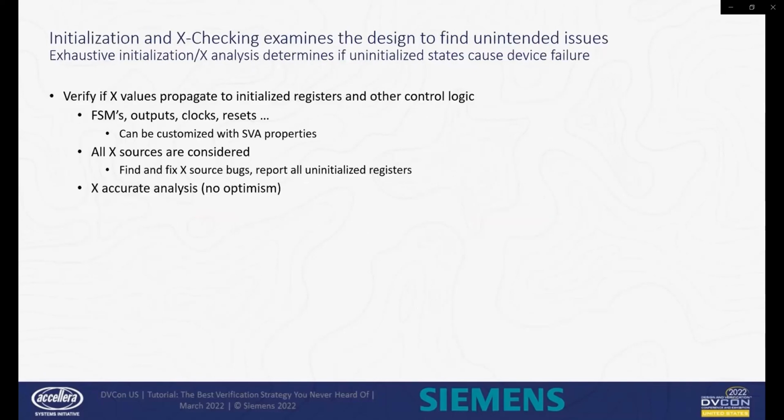Moving on to the sixth and final check mentioned a few slides ago, we check if the code is specific. Are all the items defined where needed? And will the design behave consistently? Developing a design that is clean with respect to initialization and X-propagation issues is important. There are a number of issues with simulation regarding X-optimism and X-pessimism which cause missed bugs and delays in verification. Hence, it is important to have an X-verification strategy in place, ideally before the design is integrated into the simulation environment.